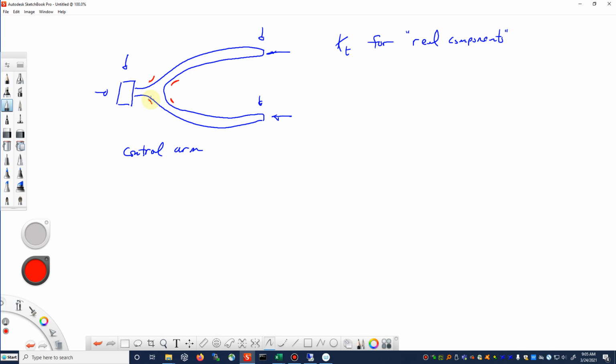Now we're going to talk about finite element post-processing for fatigue a little bit later on in the course. And when we do, please think about this example and how we're going to use the actual elastic stress at that location and not a nominal stress and a stress concentration factor. In the end, they will amount to the same thing, but the approach that we take is going to be a little bit different, kind of numerically. All right, so keep that in mind for a little bit later in our course.